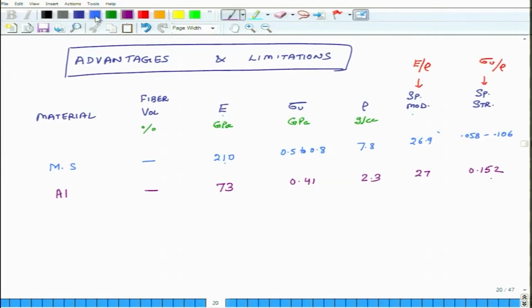So, the first composite is glass plus epoxy. So, epoxy is the matrix, and you would wonder where do I get these numbers. You will learn later how to compute these numbers, but today we are just going to discuss them. Glass epoxy, and here this composite has 57% of glass. The modulus of this is 21.5.